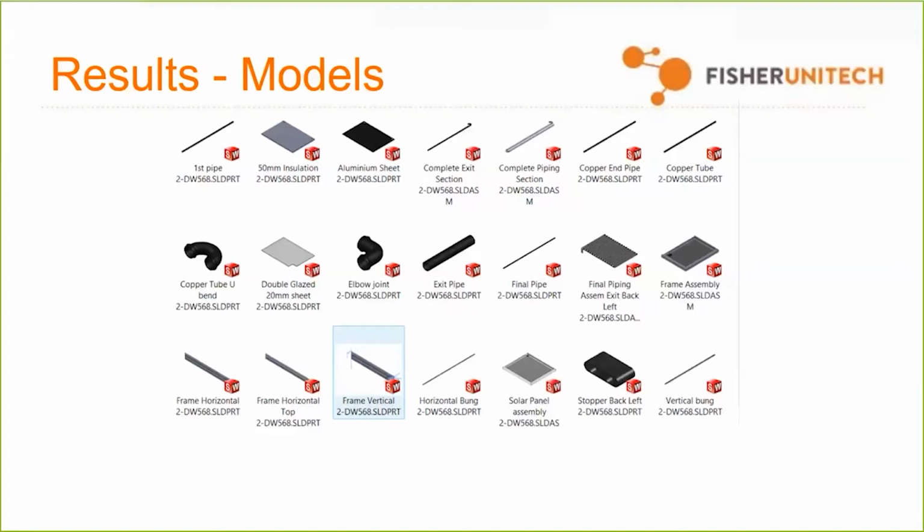So you can also put it at the beginning, or you can completely replace the file name. And one aha moment for a lot of people at this point is that you're able to put sizing information in the name of the file based upon what someone is selecting on the form. Let's say with that bracket, it was a 2x5 bracket. That could become part of the name, and then the next time someone behind you specifies a 2x5 bracket, it won't regenerate it.